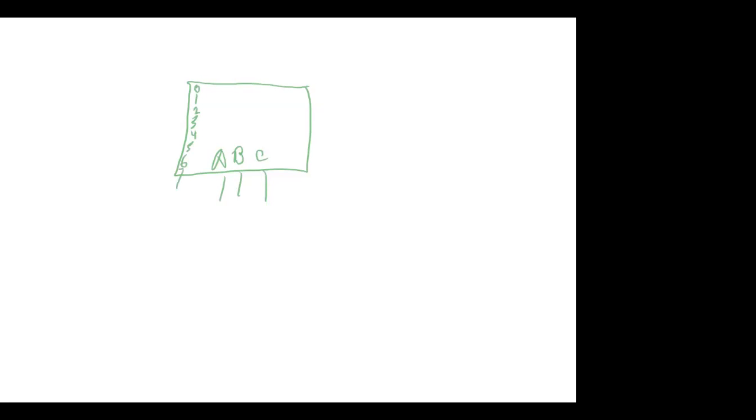So there's 7 inputs. And what we'll do is we'll take the first 3 and wire them up to ground. And then we'll take D3 and wire it to +5 volts. We'll assume that's a 1. And then we'll run D5 and D7 to the same place.